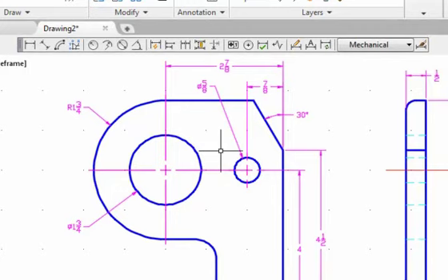Notice the radius command and the diameter command both generate leaders. We typically prefer to have the leaders at 45, 30, and 60 degree angles from the horizontal, and try to avoid having the leaders at very small or large angles. With the use of CAD systems, what used to be a very tedious dimensioning task is now much easier and faster. It is best to consider the dimensions we need for the different features, not just dimensioning geometry.